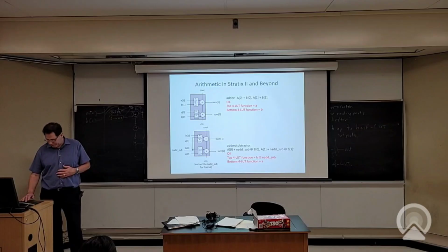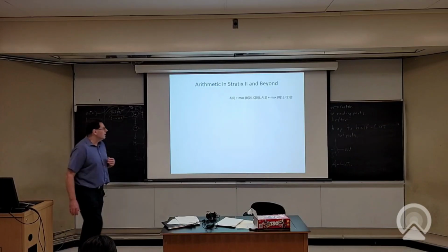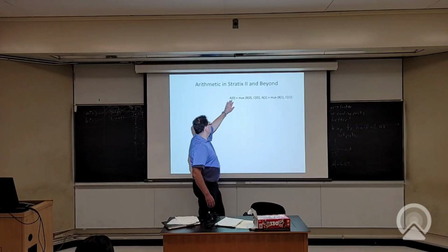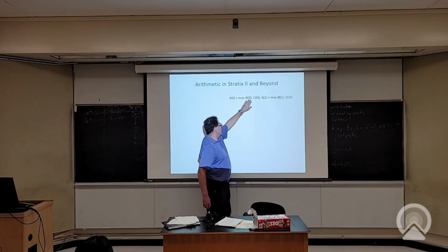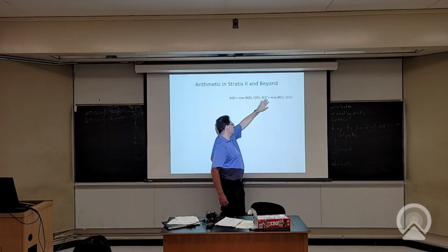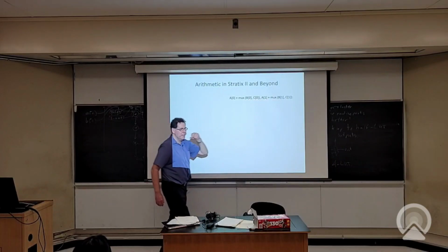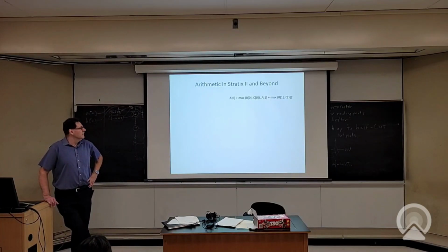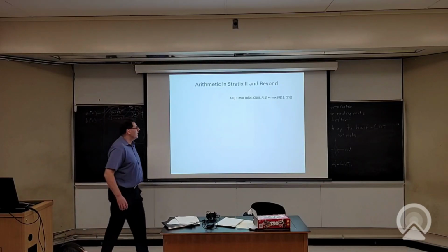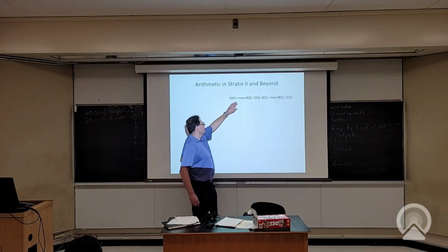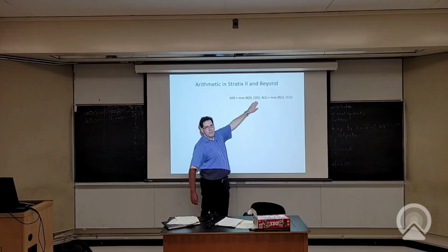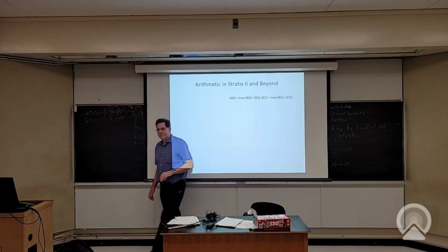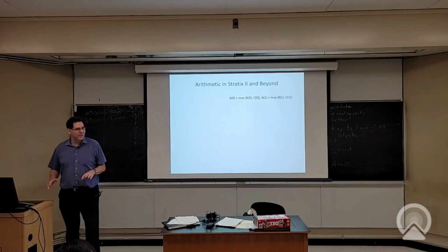So I'm getting some good use out of these LUTs. What about if I said A0, I'm going to add A and either B or C. So I want to mux between 2 different things, B or C, and then add it to A. Is that going to work or not? So you have to first think, will it fit in the LUTs? Okay, so A will fit. Can I fit the mux of B and C in a 4 LUT? I see some people nodding. Yeah, what do you think?